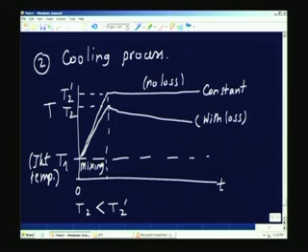Of course, in this figure it is very highly exaggerated. The temperature difference may be very small, and then it starts coming down instead of staying constant. So, this is the error. Similarly, here this is the error. If I want to calculate the specific heat accurately, I must account for this error and make it up. That means I have to add this, which is due to heat loss.